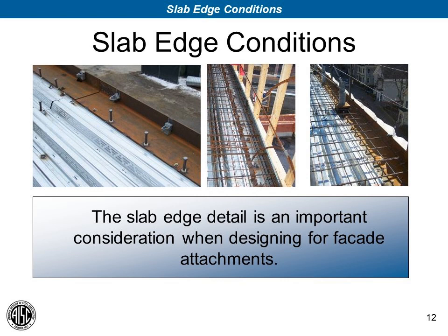The slab edges are where the facade meets the structure, and they can be some very finicky details to resolve. There's a lot of construction costs associated with these details, and relatively minor architectural and structural differences can have a substantial effect on the constructability of the system. So slab edges deserve a lot of consideration early on in the design process, and let's start talking about them right now.